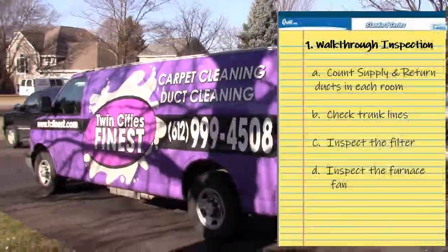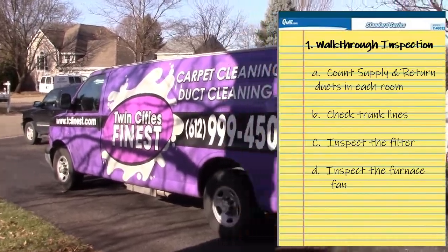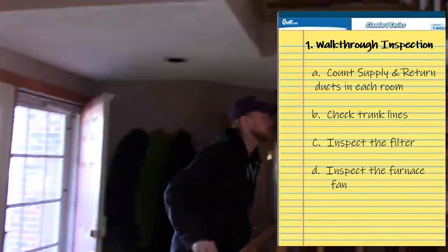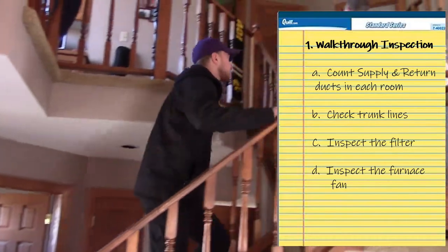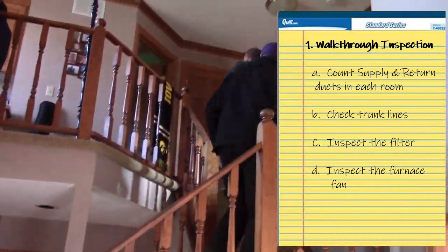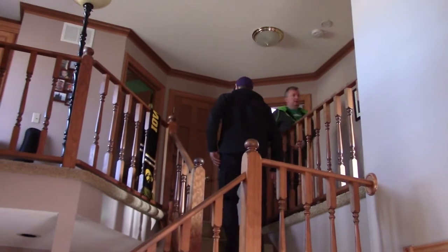Starting with walkthrough and inspection. Count all supply and return ducts in each room. Check and count trunk lines in both supply and return side. Remove and inspect the filter. Inspect the furnace fan.